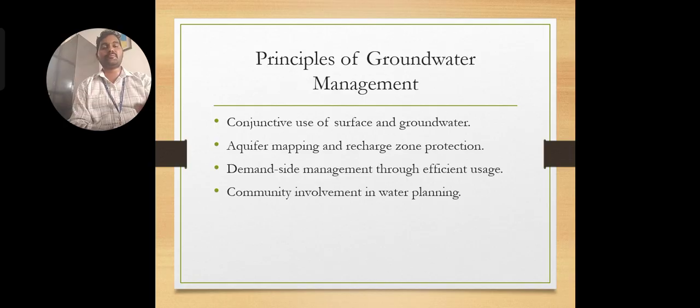Now we are going to map where the water bodies exist and where the recharge zones exist. Likewise we need to go for mapping, and then analyze what the amount of water is that we have. So likewise we go for an estimation using this also. And the next one is we are also going to calculate the demand of the groundwater at that particular located area.